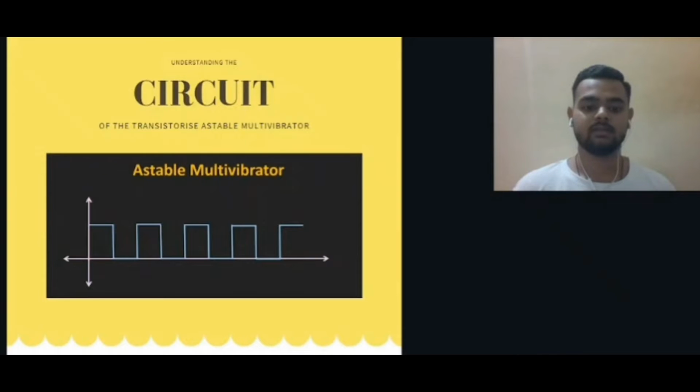An astable multivibrator does not remain stable in one state, and the output of the multivibrator continuously changes between two states. This type of multivibrator is used in the design of a relaxation oscillator. The duration for which an astable multivibrator remains in a state can be controlled by passive elements like the resistor and capacitor. At the end, the expression of the frequency is derived.